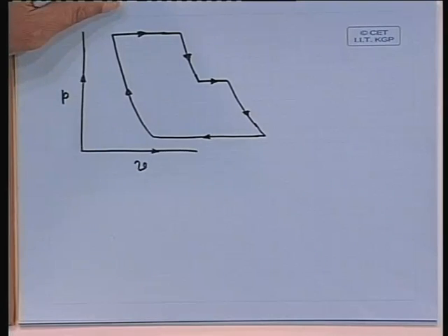Again, in that exhaust, we will burn the rest of the fuel utilizing the available oxygen there, and then it will be allowed to expand in a turbine, which can be a low pressure turbine, the second stage of the turbine.